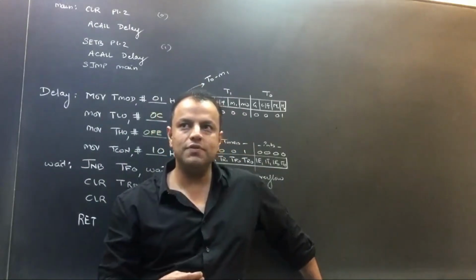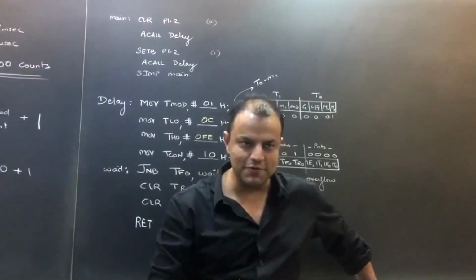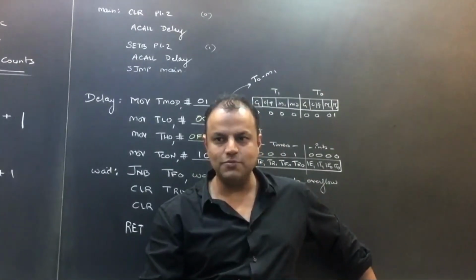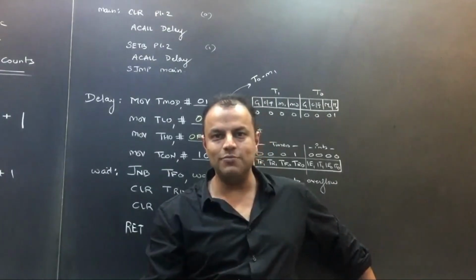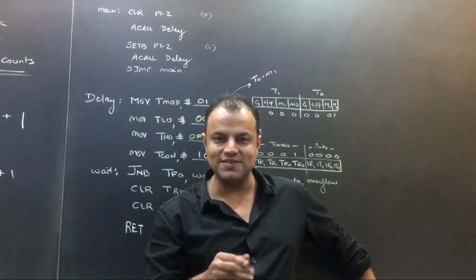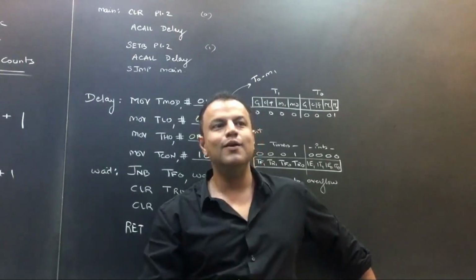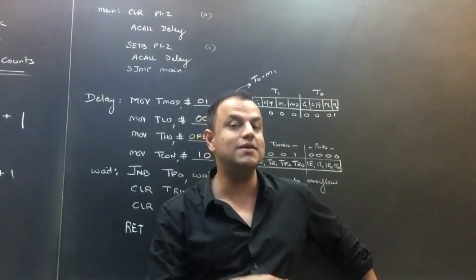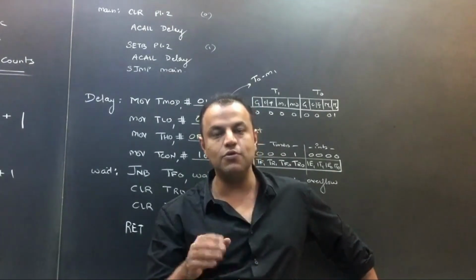Do you want to start the timer first? How can you start the timer? If you start the timer and you have not specified the mode, whatever was the previous mode, it will count in that mode. Whatever was the previous count, you do those counts. It won't even accept your new count because it's already started. So the first thing you have to do is, starting should be the last thing to do. Before starting the timer, you've got to set it up.